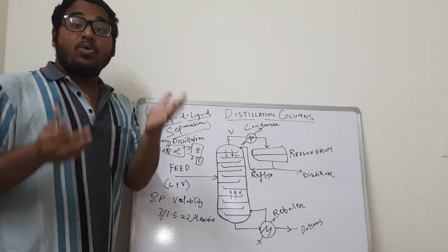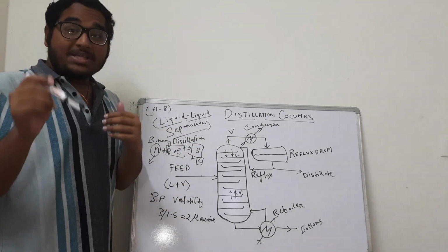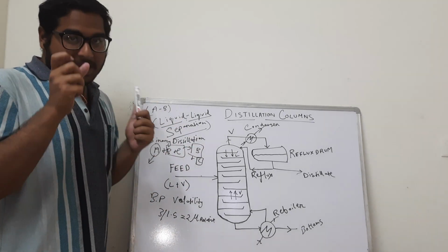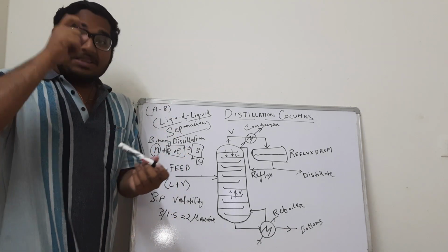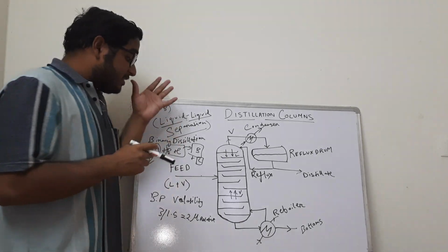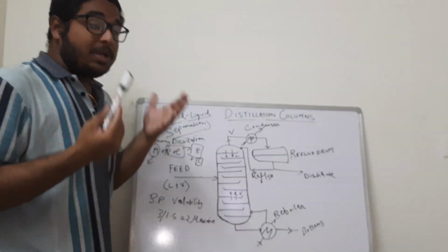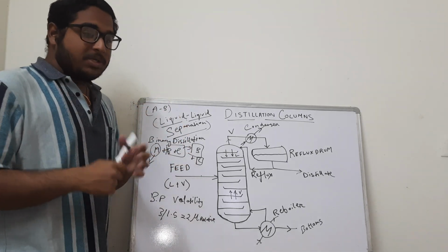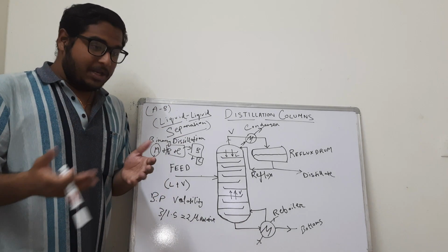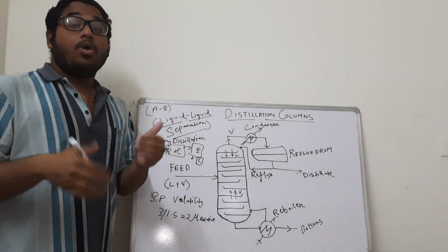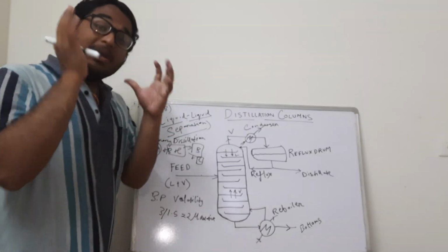So since the second compound is twice as volatile, it will have an increased tendency to form vapors, whereas the first compound, being less volatile in nature, will not easily vaporize and will have a tendency to remain as liquid. And this virtue in particular is being used in the industry, in the distillation columns, to separate two liquids, such that one liquid out of the two liquids or the three liquids primarily tries to form vapors, and another portion of the liquid primarily tries to remain as liquid.